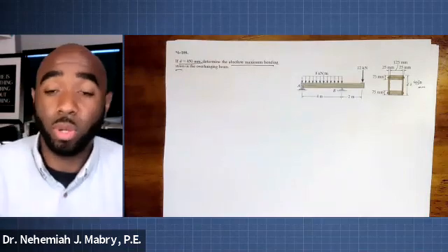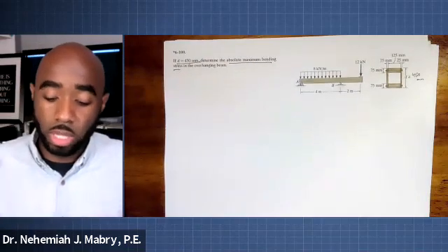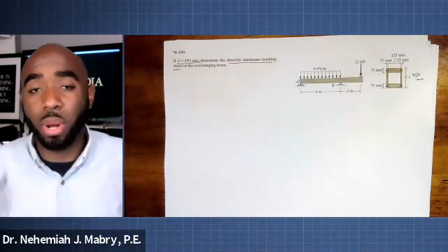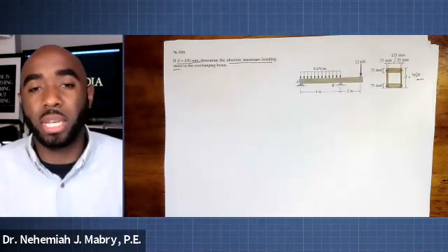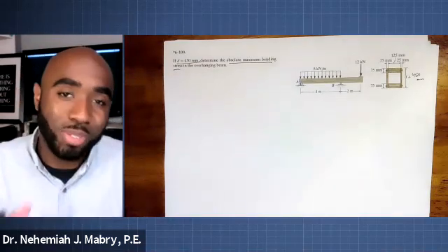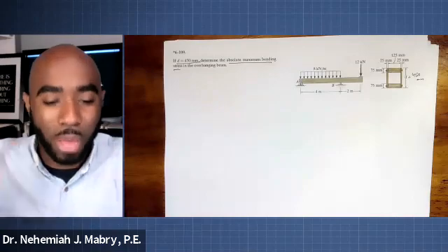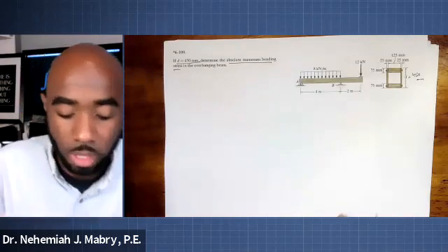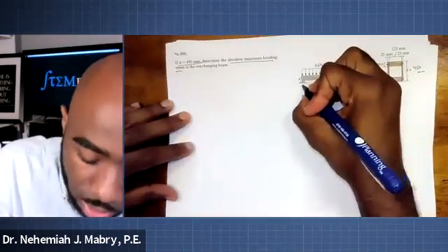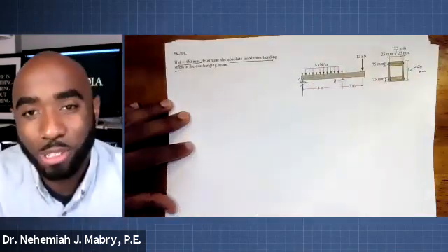So we're going to do the exact same process, right? We need to know our reactions. We need to be able to plot the shear moment diagram, find where the maximum moment is taking place, use that maximum moment in our flexural formula, and use that to find the absolute maximum bending stress. All right. So to start things off, I'm just going to go ahead and give this to you because this is statics, and by now you should know how to do it yourself.